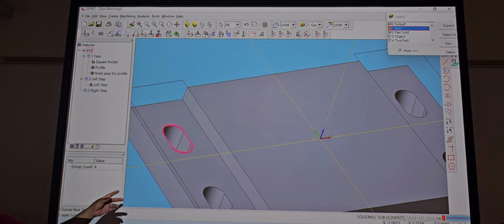I could have used contouring on that step, but I would have had to use a bigger end mill because the step over left that box in the middle of it. But if I was gonna use a tiny end mill for this, then I would want to do pocket, so it cleans up everything completely, right? So the actual tool diameter and the step over would come into play also.